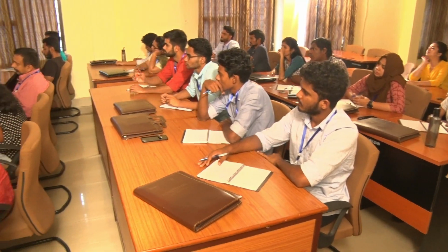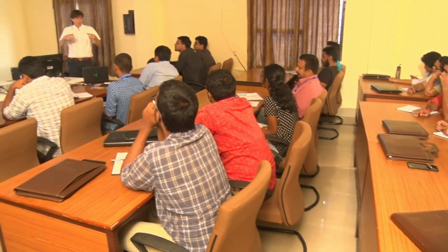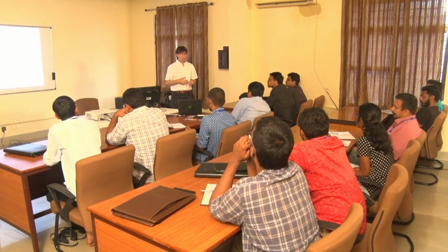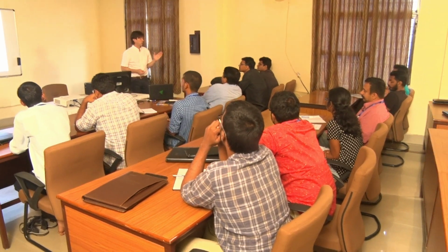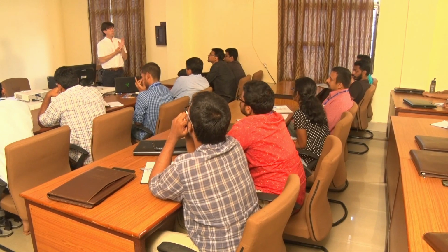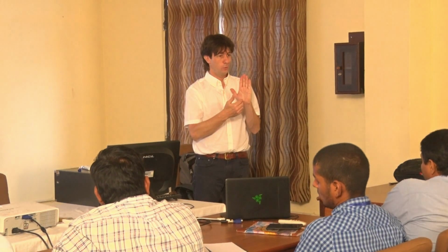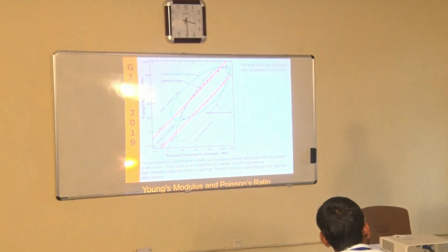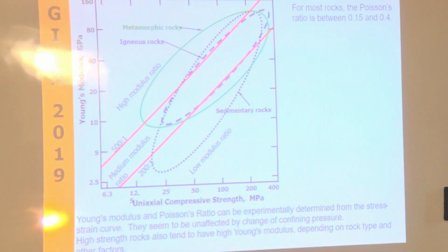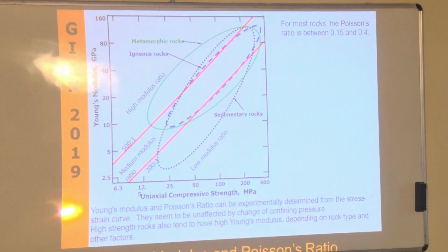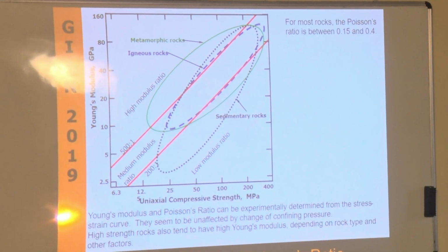And generally, the way you are using to measure the radial strains, there are several. Depending on if you use a radial chain, so a chain around the sample, and look at how it elongates, that is an average. Probably that is one of the best ways to do it. Others are using a strain gauge. This is actually a strain gauge. So it's more a point, and you hope that when you touch the strain gauge it is the right point. Very likely it's not, and so on. So there's a lot. To measure the Poisson ratio is extremely difficult, and to me, experimentally, I always have a problem.